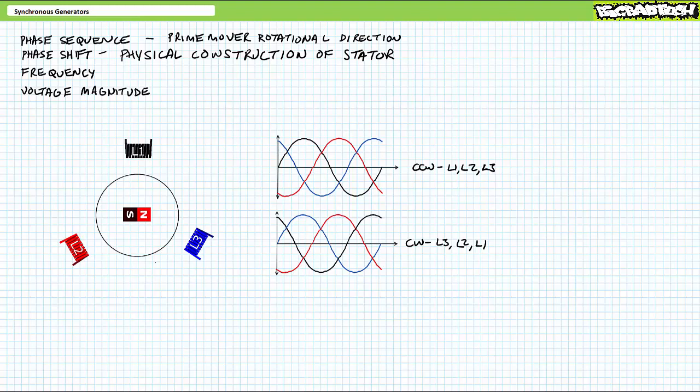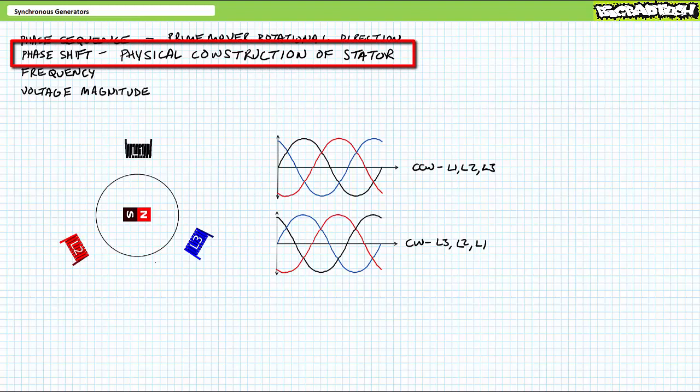This is a common arrangement for industrial 3-phase AC throughout the world, albeit not the only means of making multi-phase AC. For example, consider a 4-phase AC system with 4 windings at 90-degree offsets, or a 5-phase AC system with 72-degree offsets, and so on. In summary, the physical construction of the stator windings influences the degree of phase shift between the related phases.